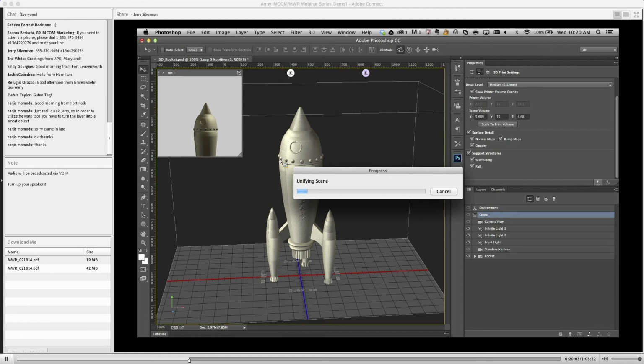And it'll also go through, while you're printing a 3D object like this, if you don't create a scaffold to hold it up as it's printing, then it'll start printing in the machine and then fall over because nothing is supporting it. So what you need to print is actually a scaffold and a little raft for the 3D object to sit on. So right now, Photoshop is generating all of that material.